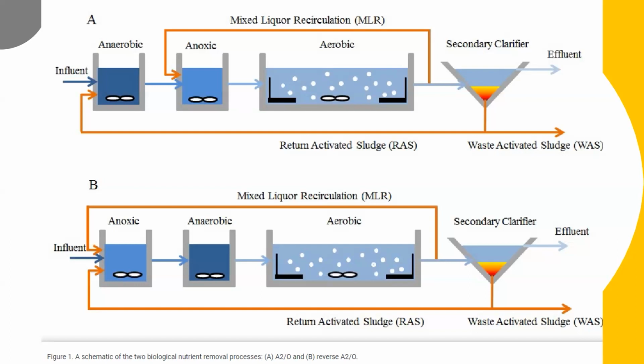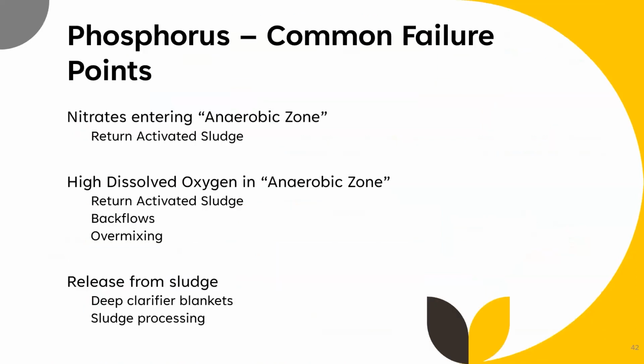If you are removing ammonia well in your aerobic zone, and you get step 1 and step 2 right, you will almost certainly have good luxury phosphorus uptake going on in your aerobic zone. So that is often not a limiting factor at most facilities.